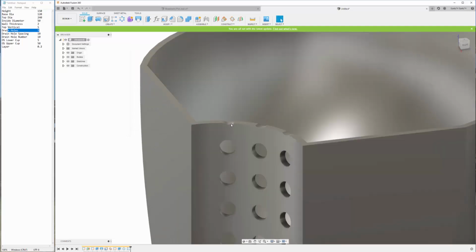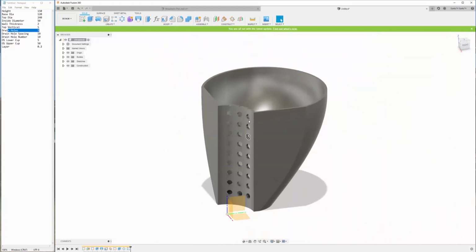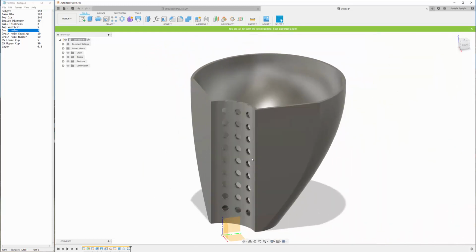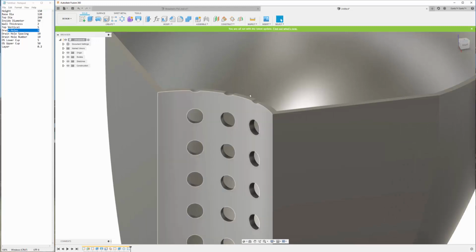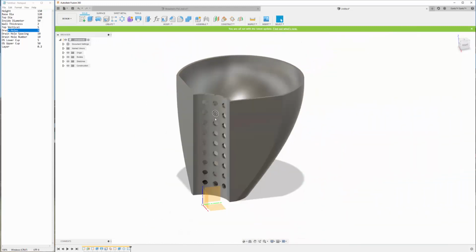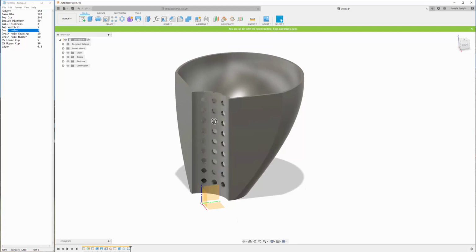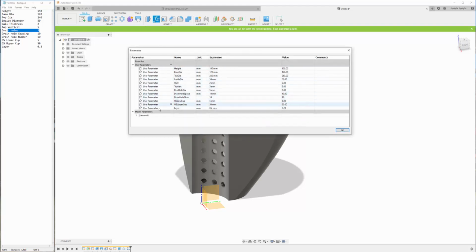We start to end up with this scenario. So what you'd like Fusion to do is actually put the number of holes in, but not actually cut like this. You always want to leave a gap at the top. So we can actually use some automation in here to define how many holes we have. If we want to get really advanced, we go into the function and we go drain hole number is